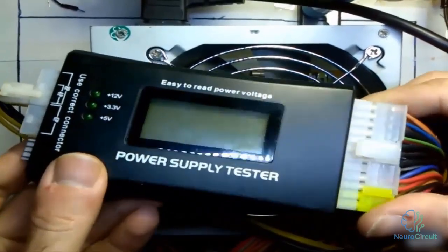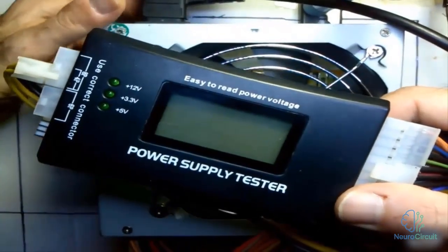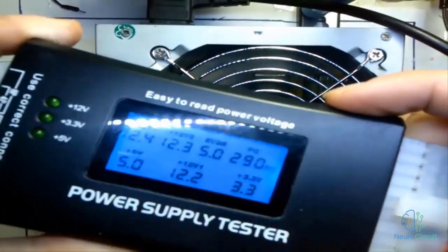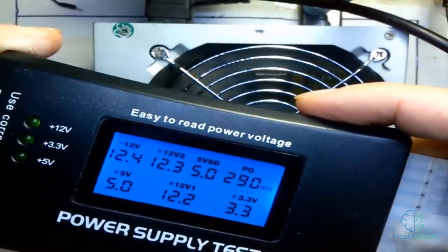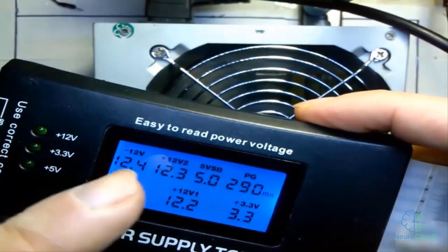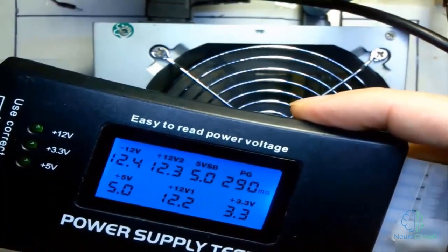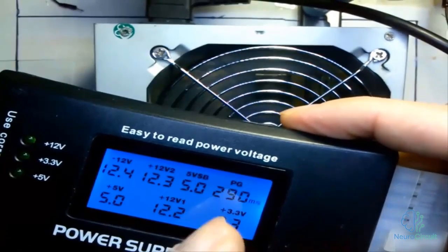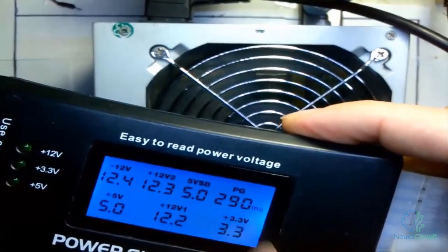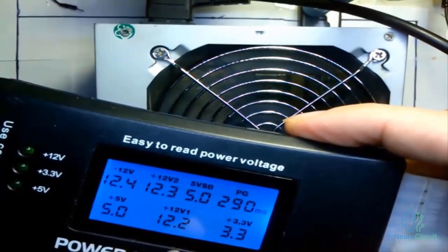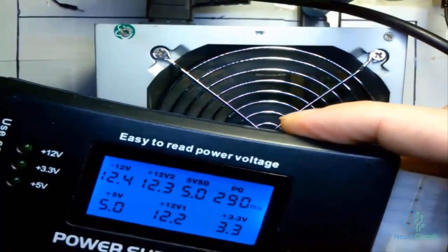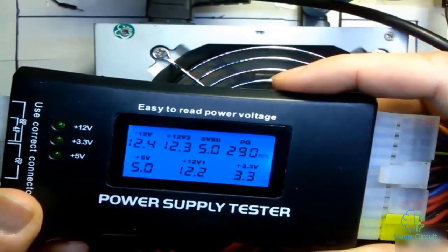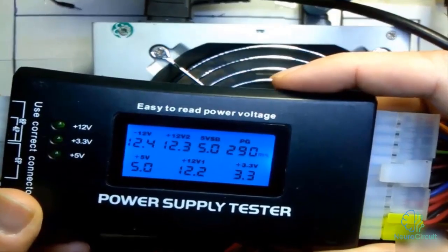After connecting the sockets to the power tester, I press the power button here to turn on the power supply. You can see that the power supply fan started spinning, so here you can see that everything is okay. Negative 12 volts, positive 12 volts, 5 volts. The standby light on this power supply isn't blinking, which means it's healthy. The power supply is good. The voltages are in the proper range, positive 5 volts, positive 12 volts, and 3.3 volts. And you can see that the power tester isn't showing any errors at all, not even a beep.